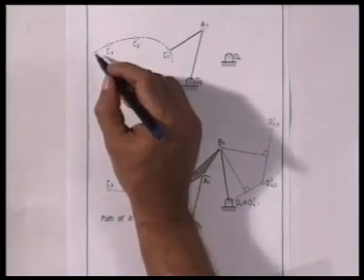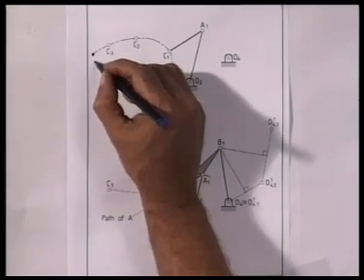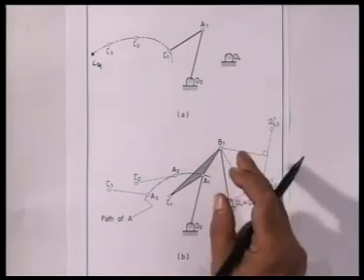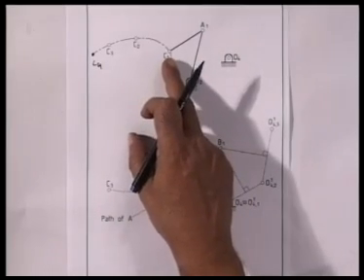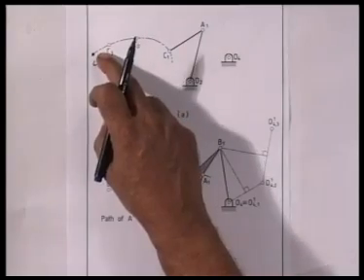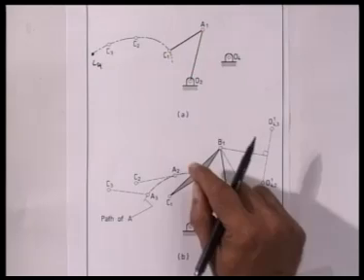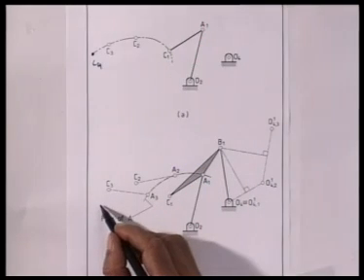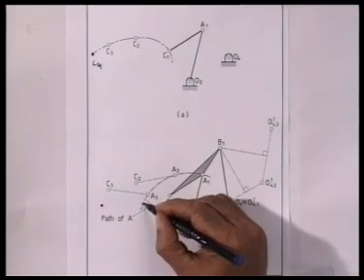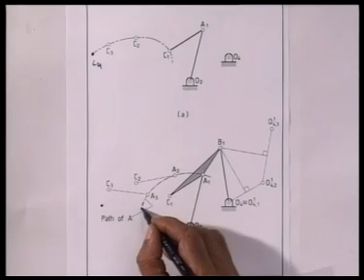If we add one more point on this, and I say it is C4. So, now I have to design a 4R linkage such that the coupler point C passes through 4 prescribed positions, namely C1, C2, C3, C4. Then with such an arbitrary choice of A1, from this location of C4, I could have located A4 on this circle, because C3A3 is C4A4, so I could have located A4.